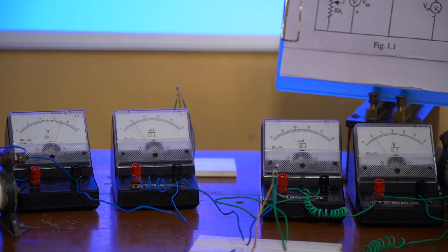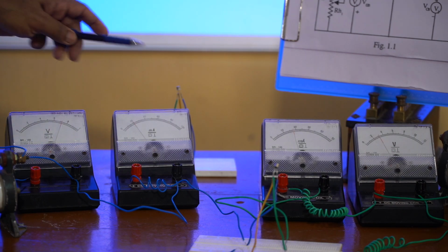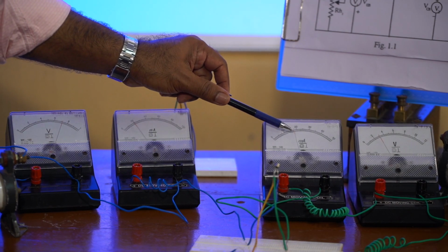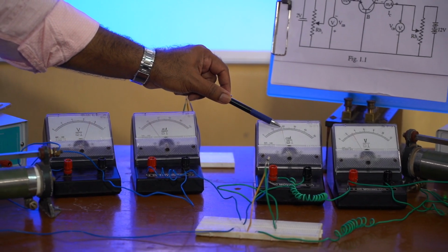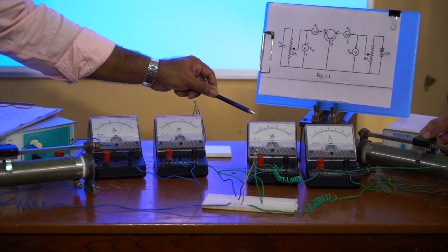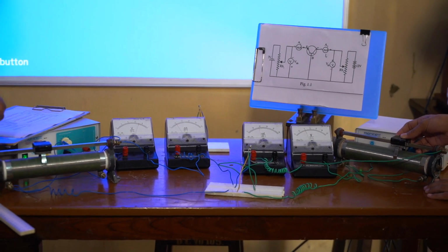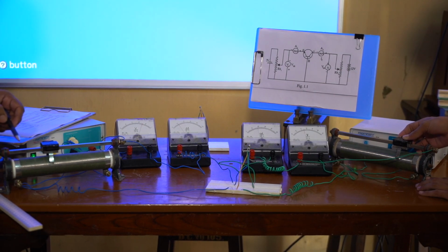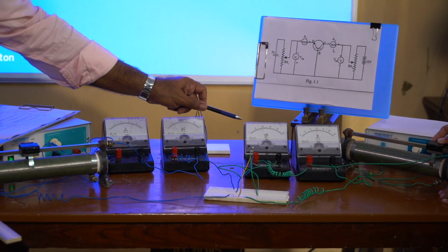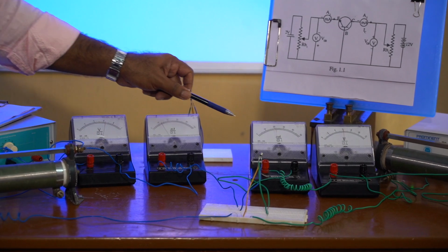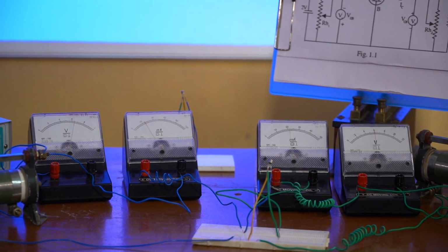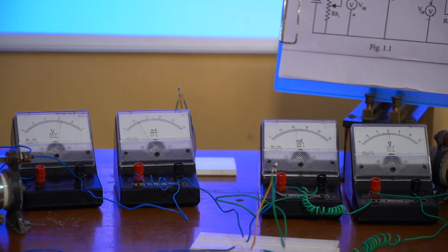Now, again change to 3 volt. Now, it is not changing. You can see that IC becomes a constant here, 19 milliampere, for different values of VCB. So, 4 volt, 5 volt, 6 volt, etc. The IC remains a constant. So, initially it starts from 17, 18, etc. Then it becomes a value of 19 and thereafter it remains a constant.